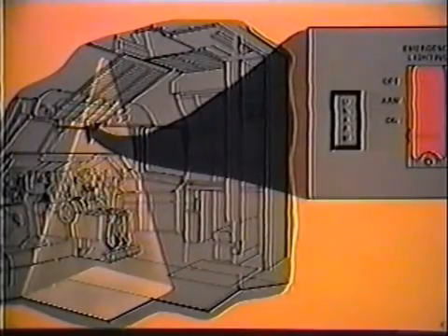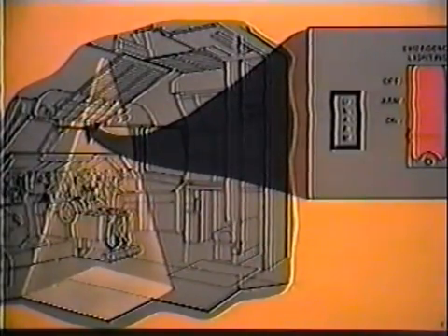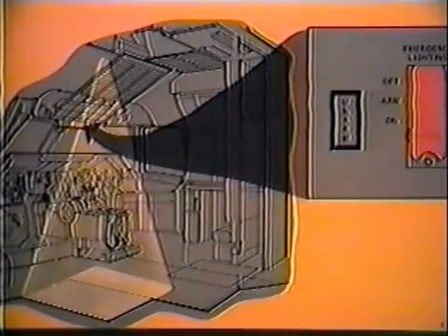In the on position, the system is activated. The flight station has a single light located above and aft of the captain. Once activated, the emergency lights will operate for approximately 20 minutes. To reset the lights or to deactivate the system, off must be selected.